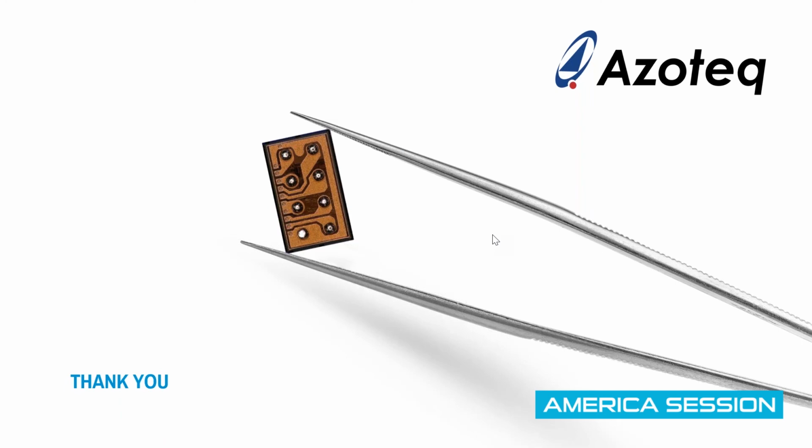I have a question on the trigger button, the amount of resolution that can be obtained. So we can achieve down to 0.5 millimeter of precision. So it is a function of the amount of travel that you have. Typically, the gaming consoles require 8 bits of resolution, and we can easily achieve the 256 positions.